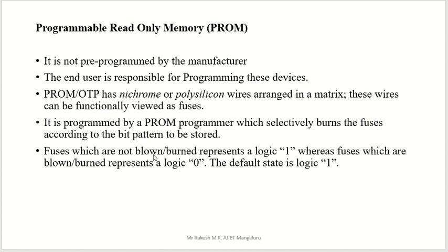Fuses which are not burned represent a logic 1, whereas fuses which are burned represent a logic 0. If you have not programmed anything, that means the memory is completely free, then your fuses represent logic 1.